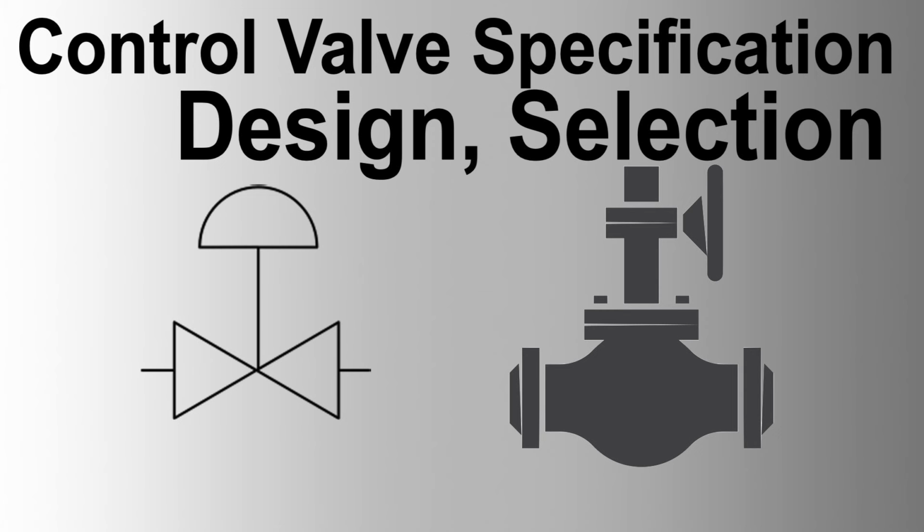6.2 Solenoid valves. Material: 316L SS body, resilient material for seat. Installation: between positioner output and actuator, explosion-proof, Ex d, IP66 rated. 6.3 Air filter regulators. Type: 316 SS, reducing relief valve type, 25 micron mesh size or less. Installation: on actuator with stainless steel pressure gauge.